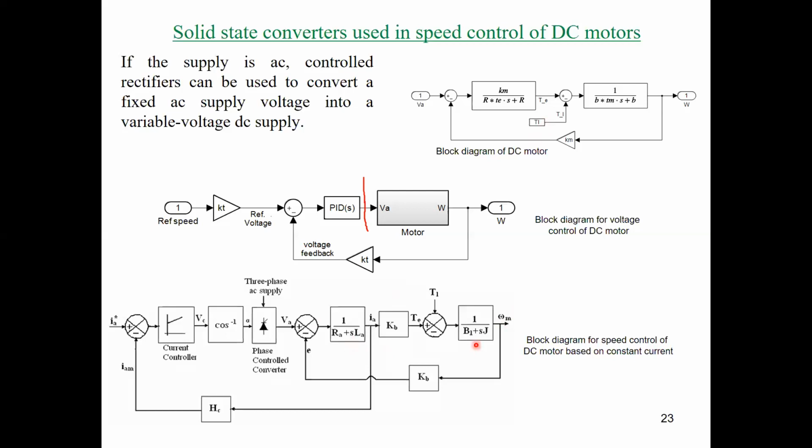We will get the terminal current, and we will use a feedback signal to control the current with a reference current. Based on that, here we will have the error, and here we will have the current controller, which is actually a PID controller as well. This will map the required voltage, which will be used with the converter in order to generate the voltage value, which will be safe in this method because the current here is controlled.